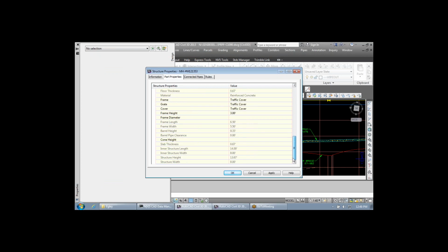So that's pretty helpful. One of the things that makes that nice, if you're doing storm drain work, not necessarily electrical work, and you have an alignment line for your storm drain, but you also want to reference the center line of the road, that can be done. Correct. So the main thing for this workflow was getting the structure offset. Well, if it's in this box, we can then add it to your label. So that was the reason for that kind of development.